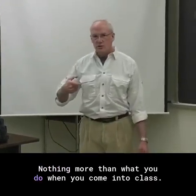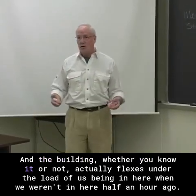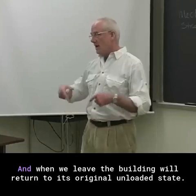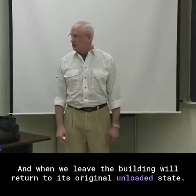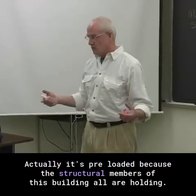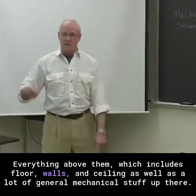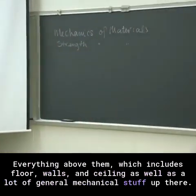Nothing more than what you do when you come into class, and the building, whether you know it or not, actually flexes under the load of us being in here when we weren't in here half an hour ago. And when we leave, the building will return to its original unloaded state. Actually, it's preloaded because the structural members of this building all are holding everything above them, which includes floor, walls, and ceiling, as well as a lot of general mechanical stuff up there.